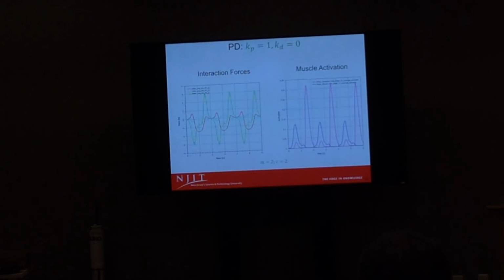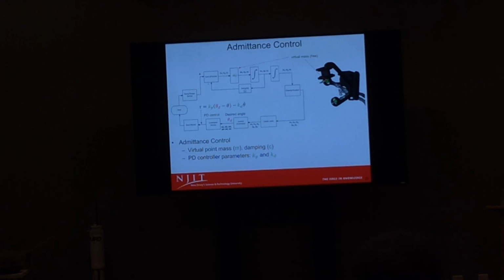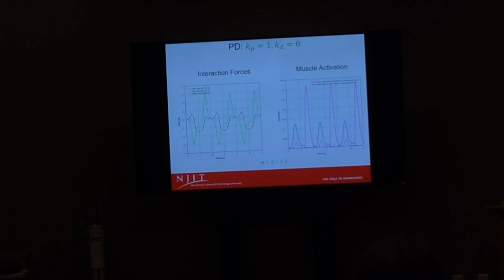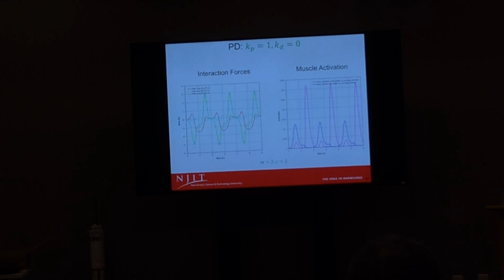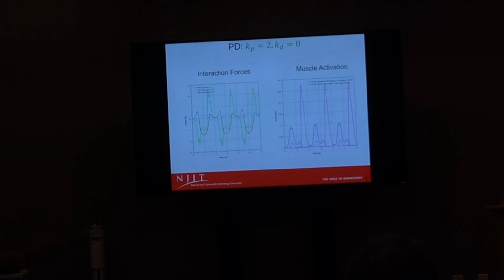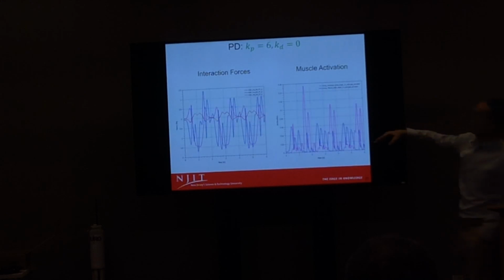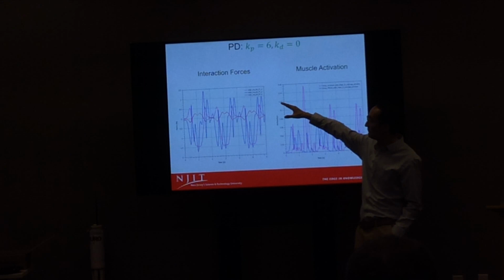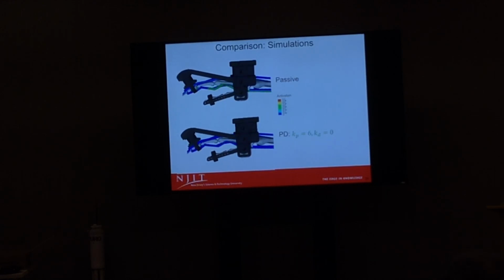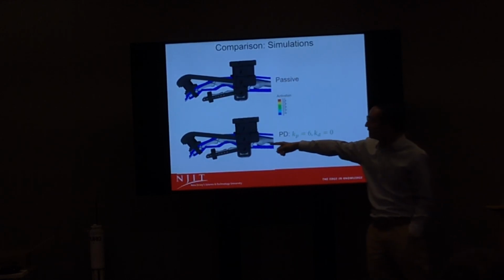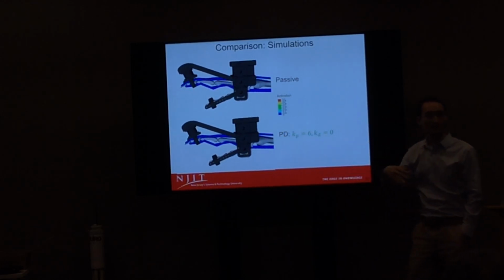So when we do similar simulations, the only thing is now we have this whole loop here. So we just try next one. Okay, it's very simple. Now we reduce the force from 4 Newton to 3 Newton, just simply by doing this control. Again, now reduce to 2 Newton. But when you keep increasing those parameters, you reduce the force to 1.5 Newton, but now it's getting a little bit of oscillation because of the feedback PID controller we use. So now this setting is good. You can see the muscle activation, especially the extension muscles, reduces quite a lot.